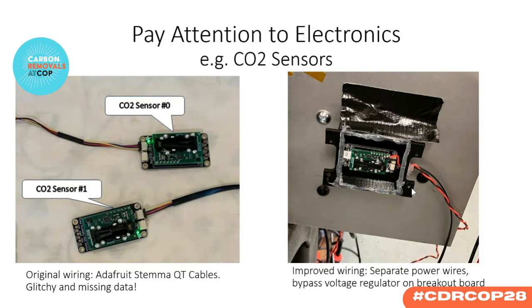Yeah, sometimes these lower cost sensors can be subject to some other effects, so that you can get more noise on them, which could contribute to some of that variability. They also could be more affected by things like temperature and vibration. So the answer may be going to a more robust or a more robustly housed sensor. It could also be that mounting them on the outside of the chamber was actually causing us problems, and maybe we need to have something that kind of suspends it inside the chamber and not actually touching the side. Right. These are all things that we can get through experimentation and through talking to the manufacturers.